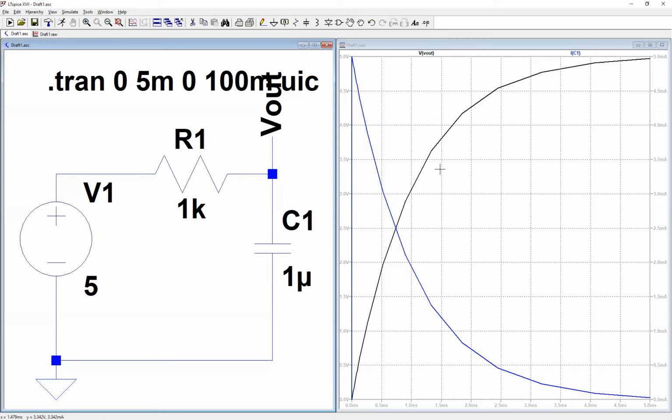As you can see here in the plot, the curve for the voltage and the one for the current are not so smooth anymore. It's kind of a piecewise linear function, a piecewise linear curve. So straight line, straight line, straight line, made by many straight lines. And this is not very nice because this is practically an approximation. So the time step that I decided before tells you the maximum time step between 2 points of this curve.